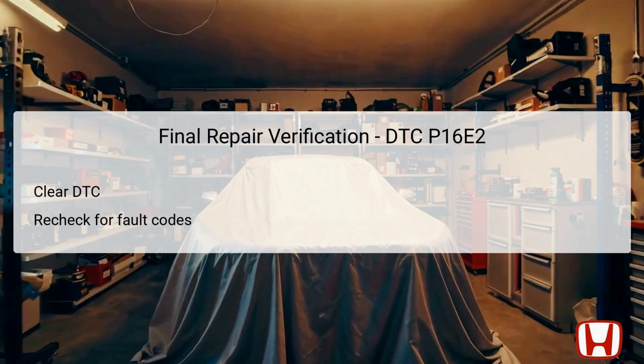After performing the necessary repairs related to DTC P16E2, it is vital to conduct final repair verification. Begin this process by clearing the diagnostic trouble code using the appropriate diagnostic tool. Following the clearing process, it is essential to recheck for any fault codes to ensure that the repairs resolved the issue.